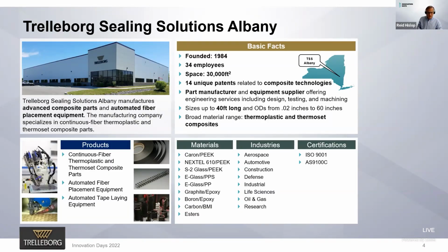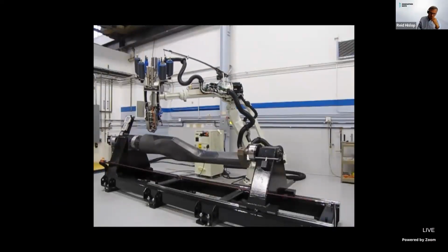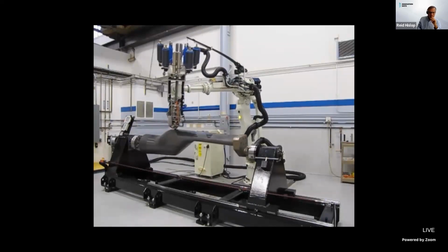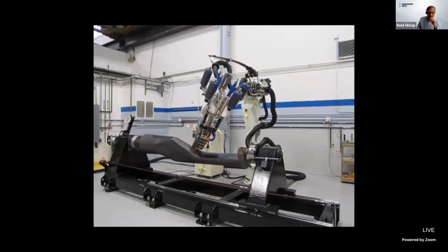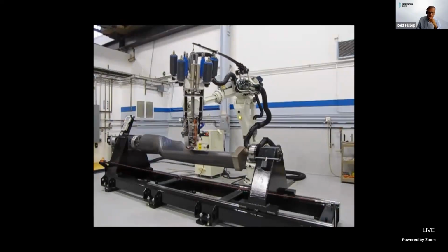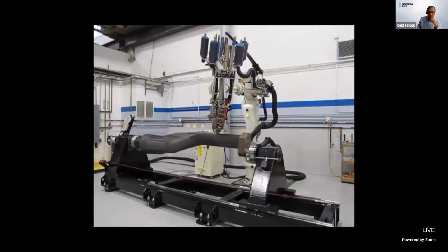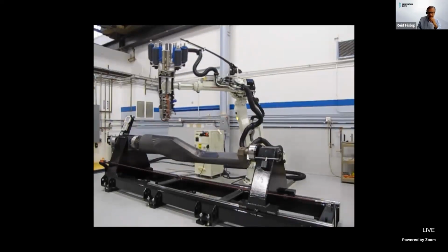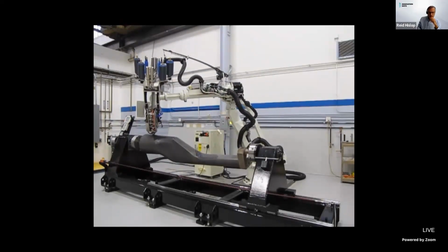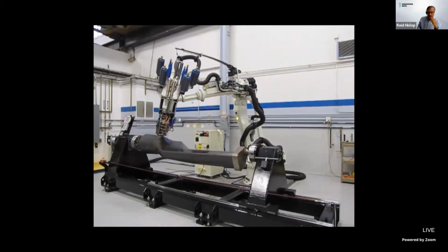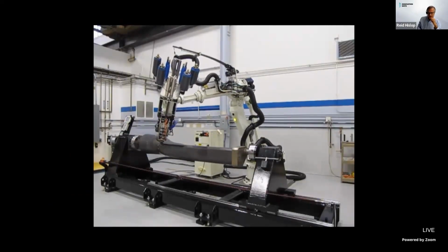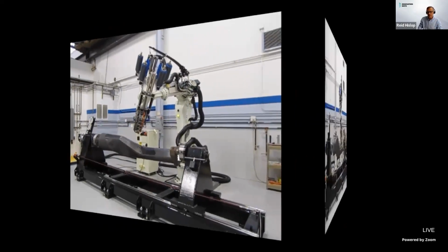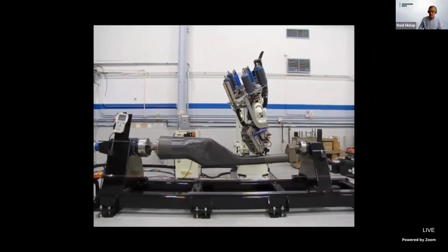So when I mention processing, what am I referring to? Hopefully you can see this multi-axis robot here. This is actually one of our work cells. You'll see on the top our pre-preg materials in a variety of different spools. Those spools feed tape into the processing head. And that processing head provides a combination of time, within which it's laying down pre-preg materials, temperature, which is at the material's melt point, and compaction to produce a fully consolidated part. So there's no post-processing required.